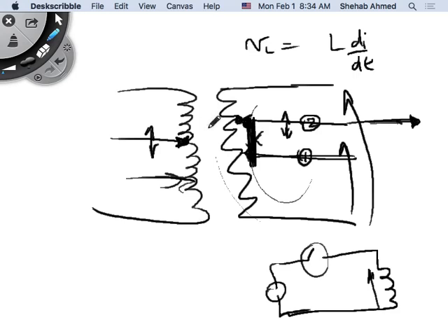So I put a short circuit across the two taps. So I short circuited the windings for a short while, right? Which is not good for the windings. It will heat them up, but they're rated for that, right? The on-load tap changer or under-load tap changer would definitely be more expensive than an off-load tap changer transformer, right? So they were more expensive.